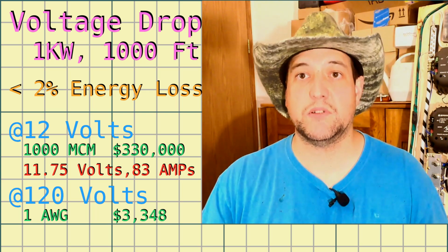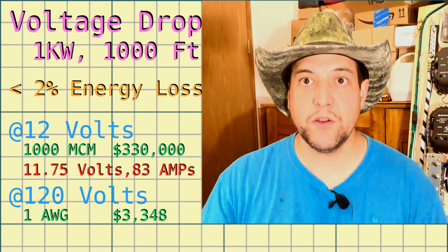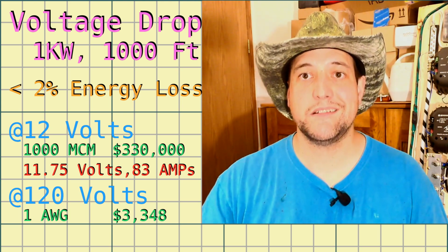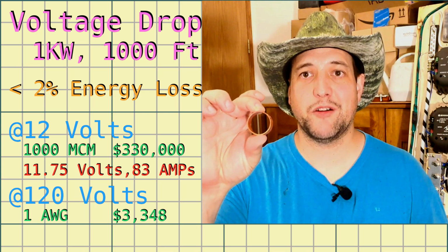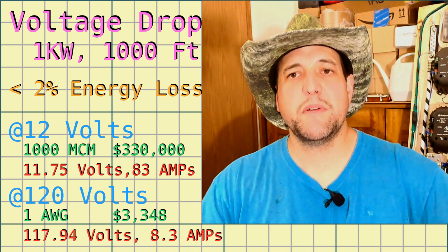A bit more reasonable, you know. Still a very expensive air conditioner for a little tiny shack, but we can do that a lot better. Plus, can you imagine running 7 bundles on both sides, going down a huge conduit to get this thing hooked up? It'd be crazy. Now the voltage at the other end would be about 117 or 118 volts. Hey, that works perfectly fine. Lots of houses have that kind of voltage and all their stuff runs. Oh yeah, that appliance would work, no problem. Voltage drop is extremely important when calculating and figuring stuff out.